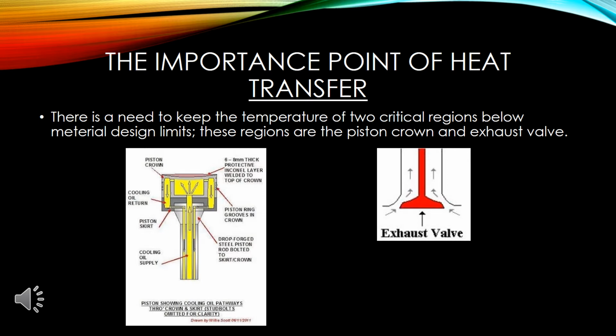Firstly, I will talk about the importance of heat transfer. There is a need to keep the temperature of two critical regions below the material design limit. These regions are the piston crown and the exhaust valve.